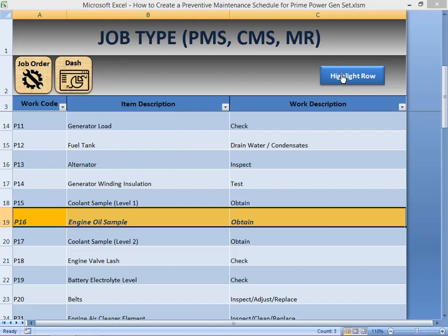Diesel fuel also passes through the piston ring and mixes with the oil in the engine oil sump, or crankcase, or engine pan. In my experience, the maximum fuel sulfur should be around 1%. If it is 1% or less, that would be okay. That would be good, so maintain the frequency of changing the oil.